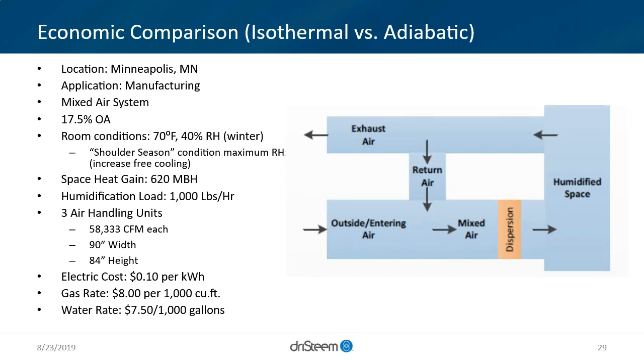There is an additional pressure drop with the final evaporation media, which we'll talk about in components a little bit further. And then that water cost, not only the water we're putting in the air, but the water from evaporation efficiency and from our different components upstream, like an RO system and the pre-treatment.